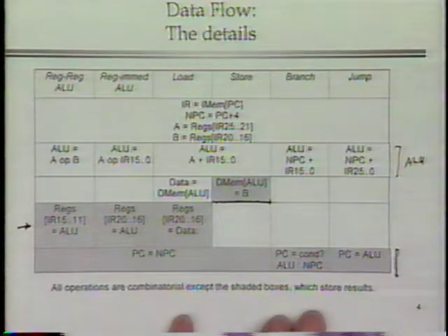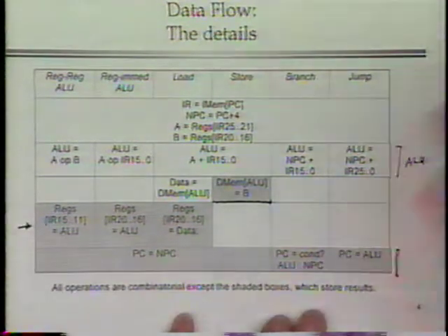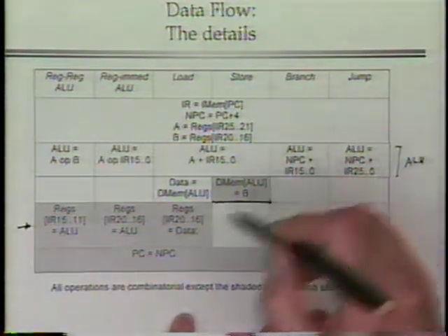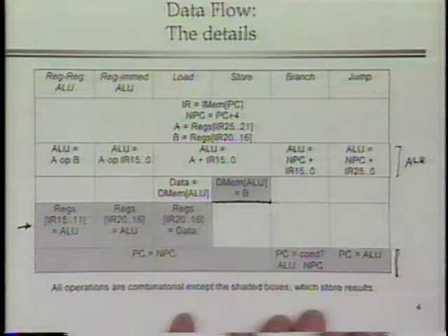So in fact, this could be a one-cycle implementation of the DLX instruction set that simply clocks out the current instruction, waits until all of the propagation through register files and ALUs have finished, and then issues a clock that puts the results into registers, memory, and the next PC.